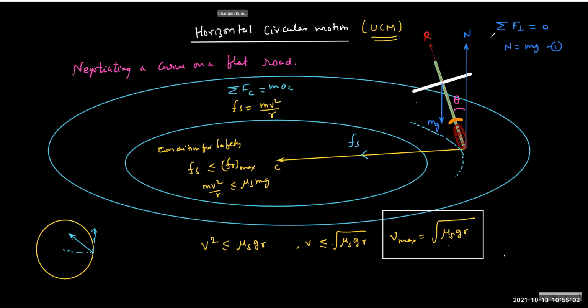So it is natural for the body of the vehicle to align itself along the resultant R, because if the net reaction force does not pass through the center of mass, the bike will wobble. It will start shaking and you will lose control eventually. While watching a MotoGP race, while turning, many lose control and the bike starts wobbling and you cannot stop it. That's not in your control because friction will be very variable, in a random direction. So the tilt is natural so that the net force passes through the center of mass.